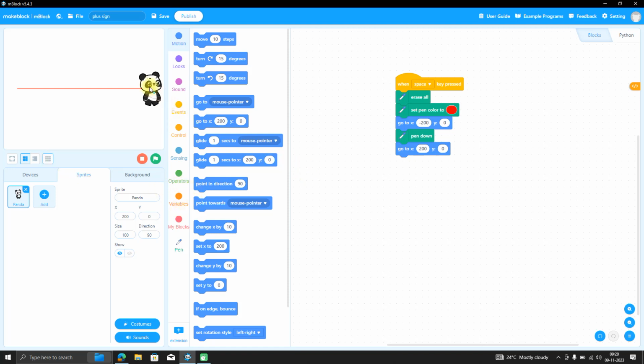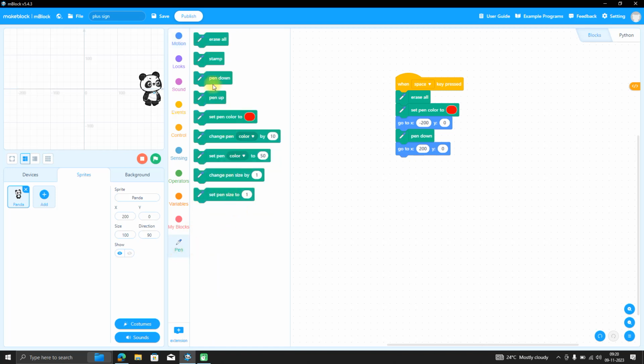Again we have to do pen up from this point, put the pen at this position, and then draw a line like this in the downward direction. So we'll consider these two points also, this one and this one. At this position the value of x is 0 and the value of y is plus 200. So we can take the third point. Firstly we have to do pen up at this point.